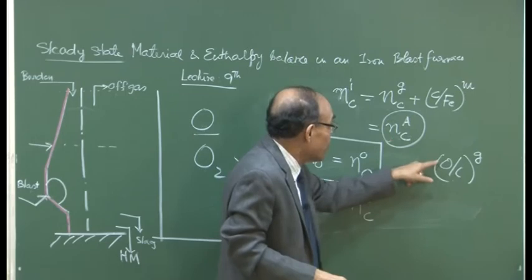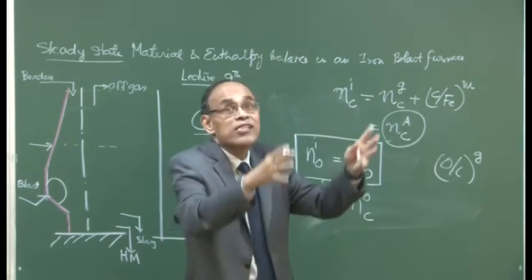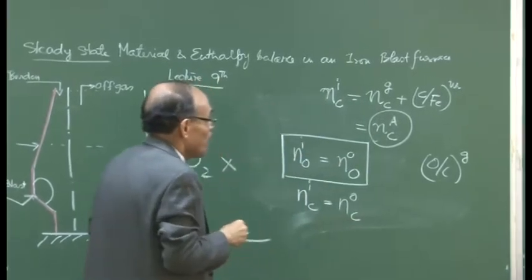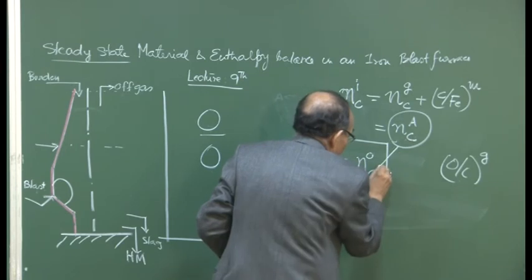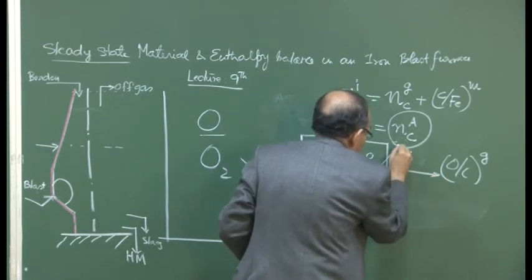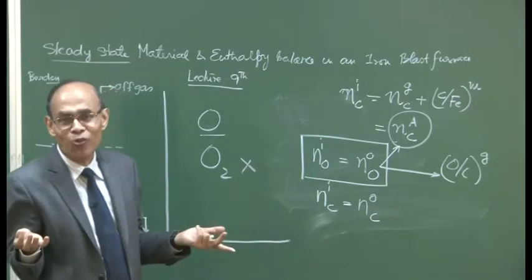Okay? If you multiply the two, that gives you a measure of oxygen on a molar basis which is sitting in the top gas itself. So therefore the output can be expressed of oxygen for the idealized operation and even for non-idealized operation, because where will the oxygen go? Okay?